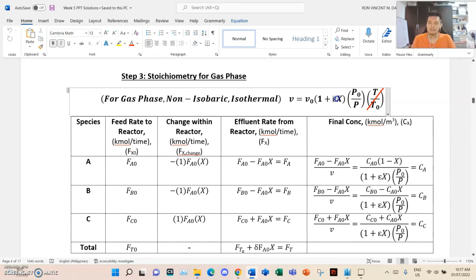And for liquid phases, this value essentially equates to 0. However, we assume that it is not a purely liquid phase reaction since we're mixing gas and liquids, so we'll just assume it to be a gas phase since the reactant is in gas or vapor form. Hence this value cannot be equal to 0 and we need to calculate this manually.